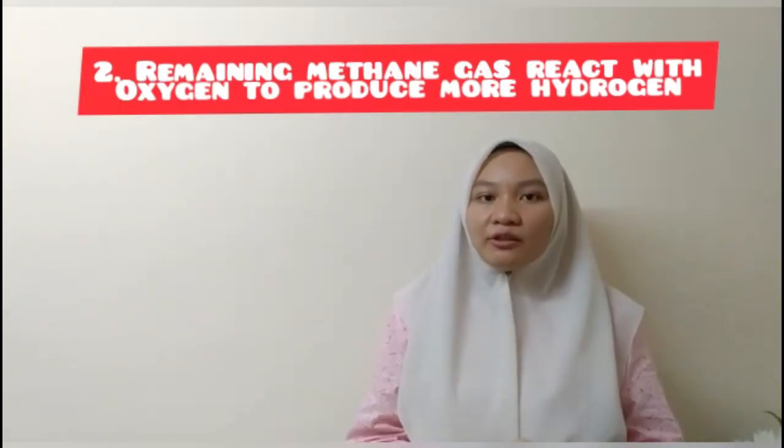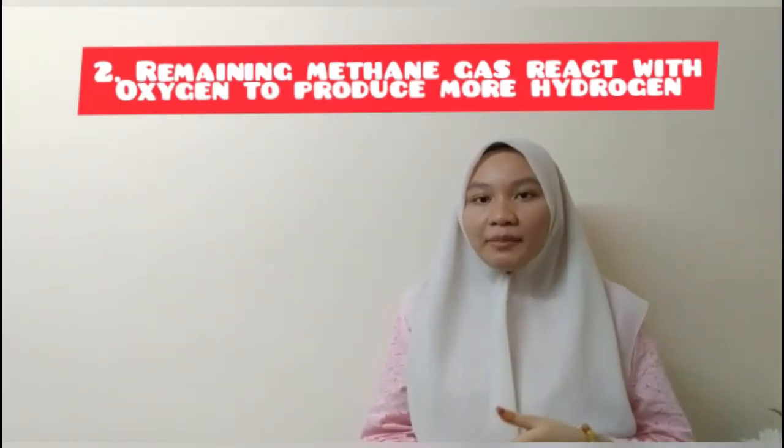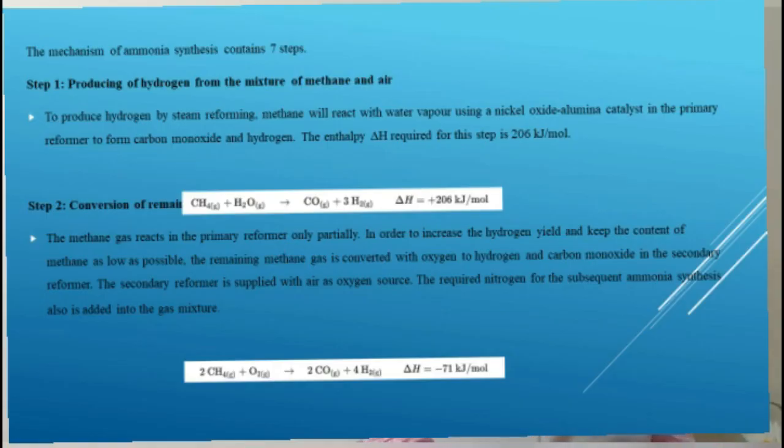For the second step, the methane in the primary reformer will only react partially. So the remaining methane gas will react with the oxygen in the secondary reformer. The secondary reformer is supplied with air as the oxygen source. In this reformer also, the required nitrogen is added into the gas mixture.